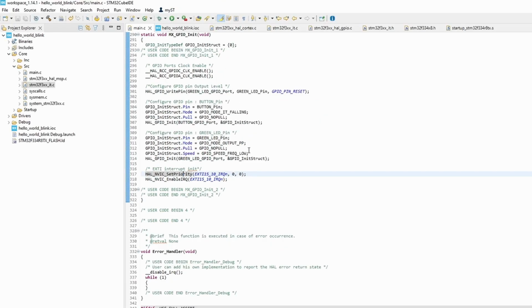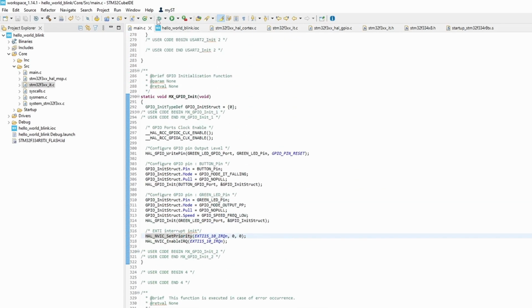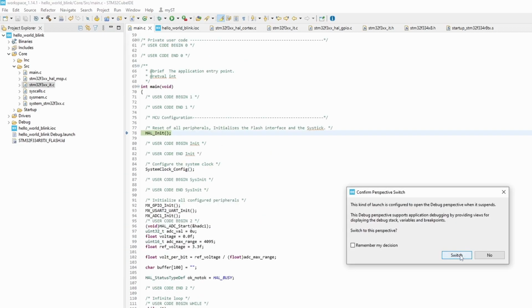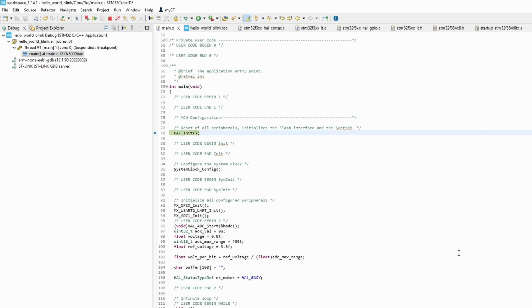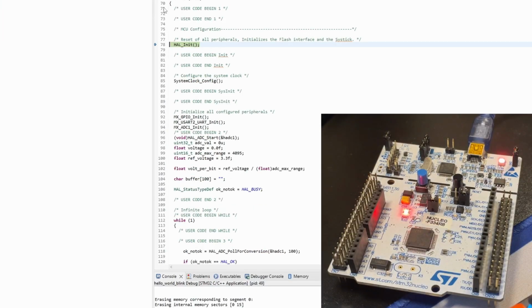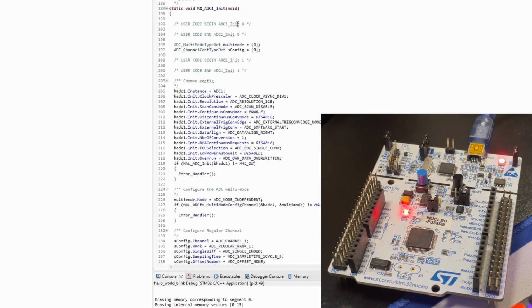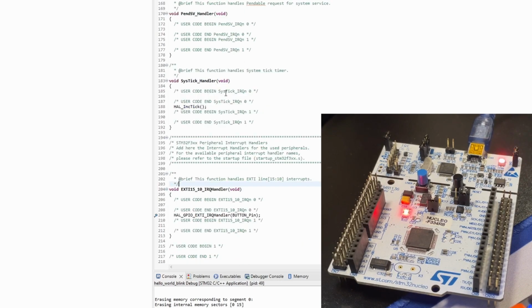and go back to our main, and we can test this is working first of all before we move any code. So if we switch to the debug perspective, I will set an overlay so that you can see me pushing the button, and hopefully we should end up bouncing into our breakpoint in here.